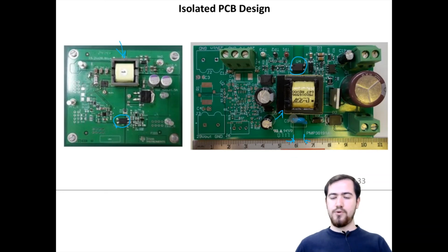We need to provide some clearance region between these isolation paths, otherwise it constructs another capacitive path to carry the current, and this path can distort our signal for analog measurements or digital PWM signals, etc.